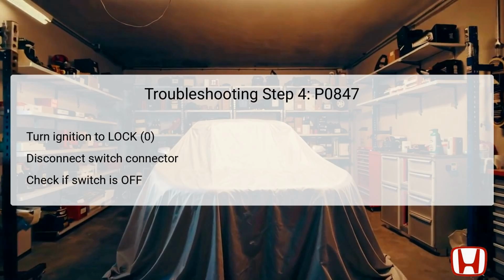The goal here is to determine if the pressure switch now correctly indicates an off status. If it is off, this condition suggests the switch is faulty, necessitating a replacement as it doesn't align with the expected behavior. Conversely, if the switch remains on, further investigation into the circuitry is required to ascertain why it's not responding correctly.